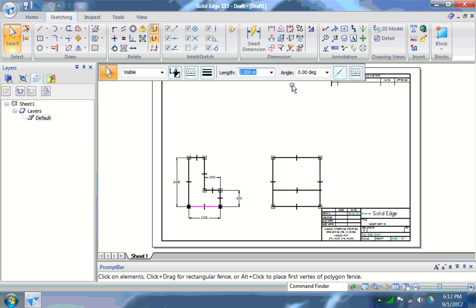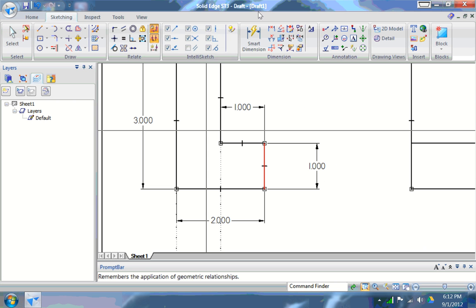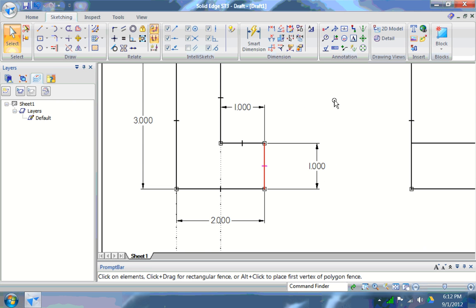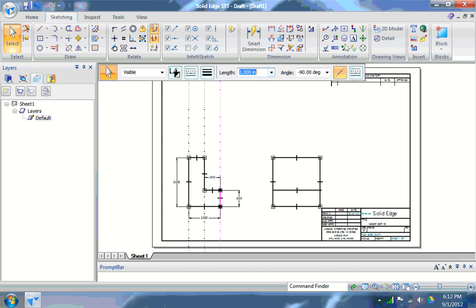There we go. Now I want to draw the top of it the same way, and that goes above the drawing, and then hit project line. Again here, project line. Again with this one, if I can select it, we'll just zoom in on it again and select project line, fit the screen. There we have it.